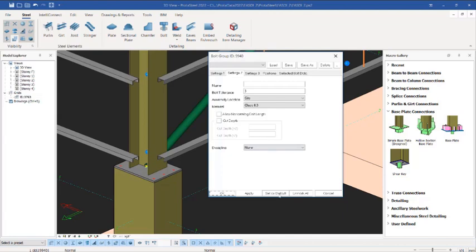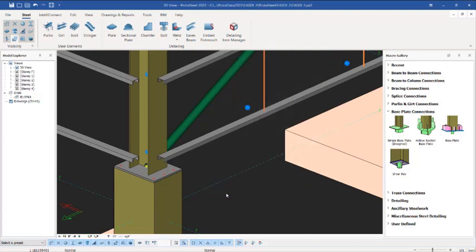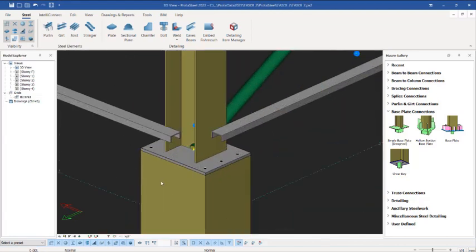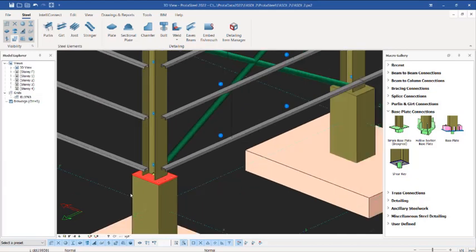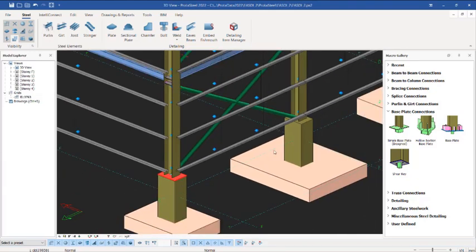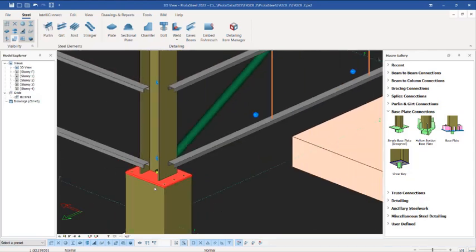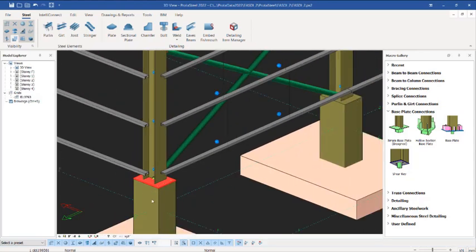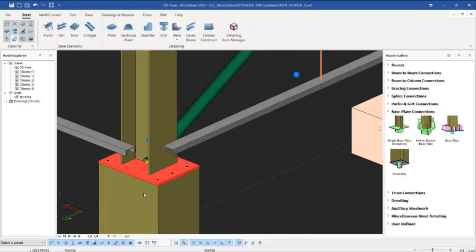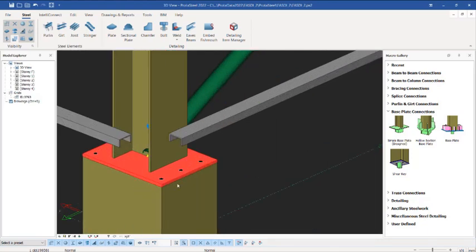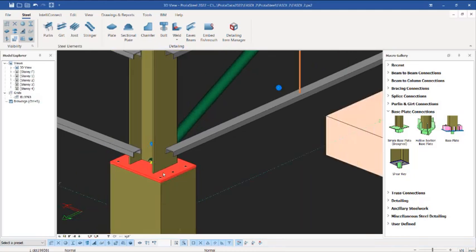So I will click on the OK option. We are done with this. What we need to do now is copy this to other ones in the same orientation as this. The point there is that if you copy, you must cut, so that it will not clash with the reinforced concrete columns. But at first, let us bring in the anchor bolts, which we will be considering.